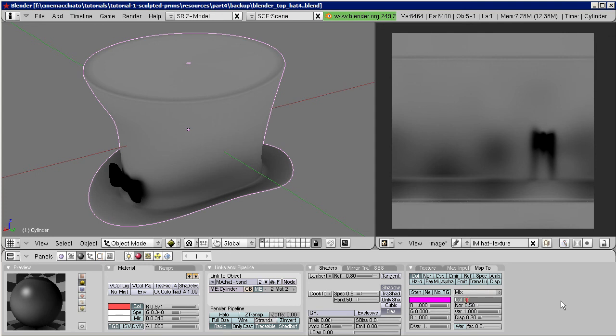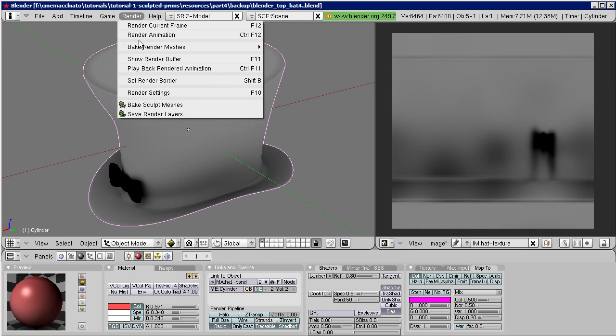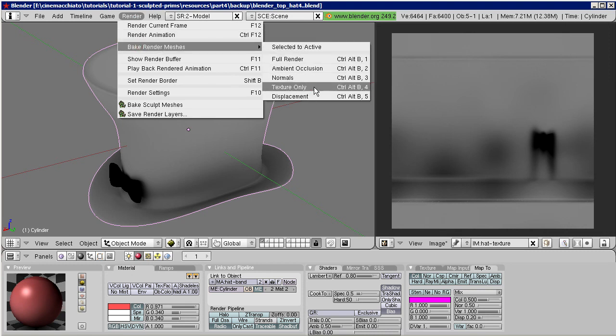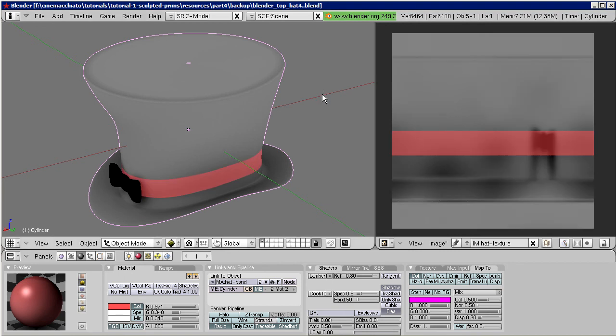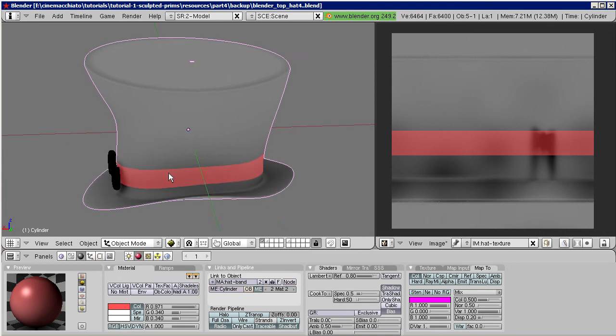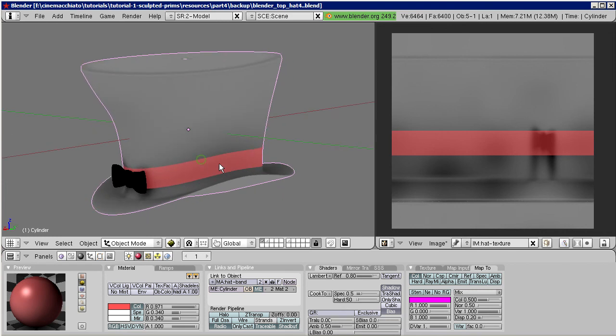The simple solution is to change the mix value to 0.5, which would do what the name implies. It mixes the base material and the ambient occlusion map, both with an amount of 50%. But this option creates washed out textures. An enhancement could be to use blend mode overlay for the hat band, and set the color value to 1.